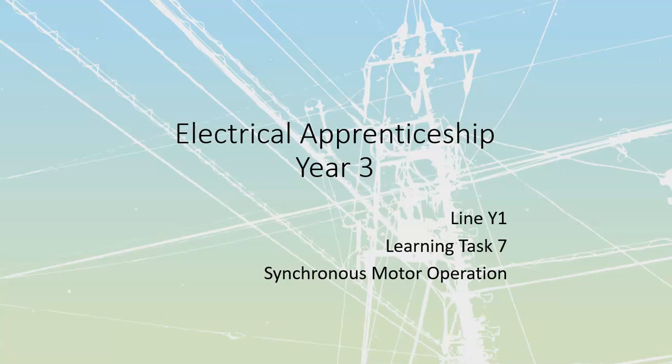All right, line Y1, synchronous motor operation. We are going to take a look at synchronous motors as capacitors at this point, just because we know that we have the capability of overexciting these things so that we can drive them into that point where we are going to have a leading power factor. And we talked about that in the previous video.